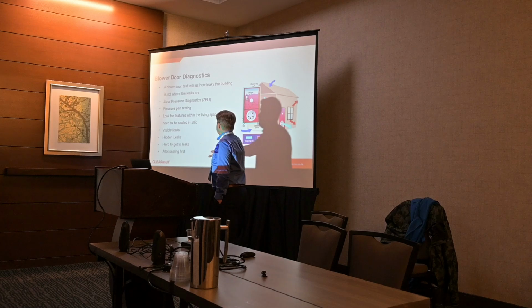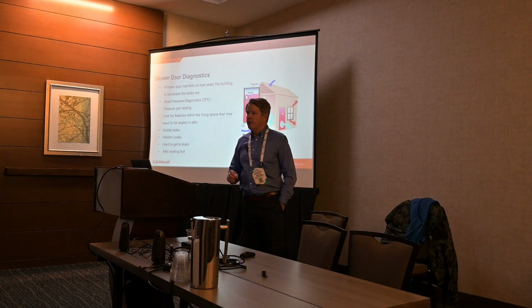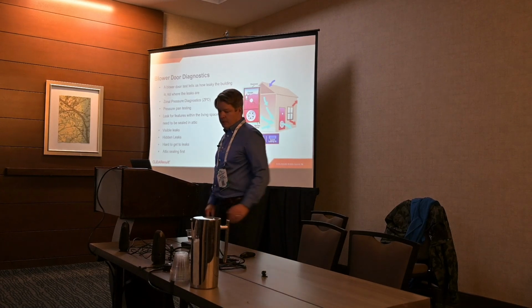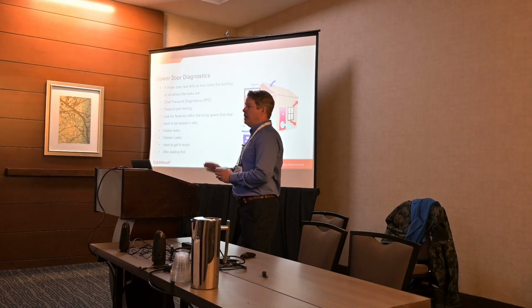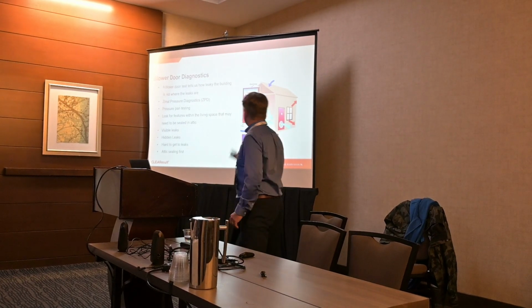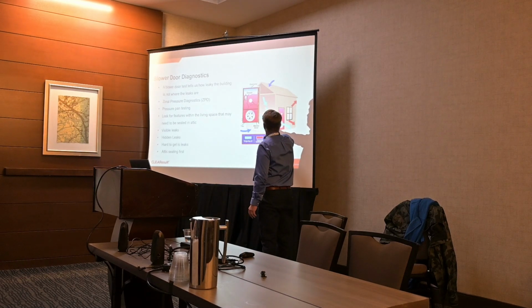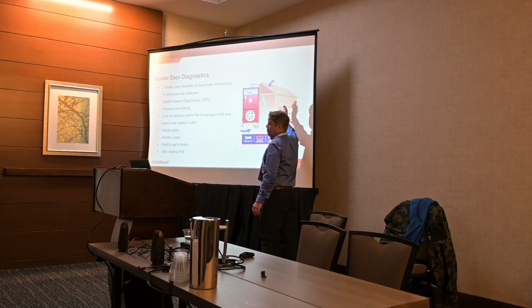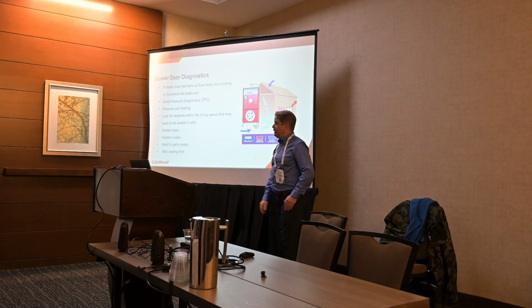We always do our air sealing. We always start high, right? Why do we always seal high in the house first? Stack effect, yes. Stack effect is the dominant way that a house leaks. We also have wind and we have mechanicals, but stack effect is always going on. So that means the leaks high and low are the most important. Not that the ones in between aren't, because when it's windy, they will leak, and when mechanicals are running, they'll leak. But it's high and low first, and then if there's opportunity and time, seal the ones in between.